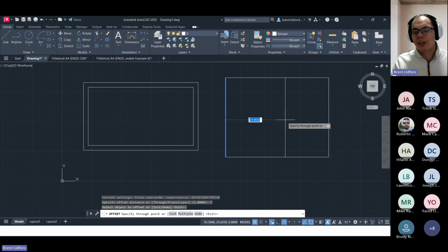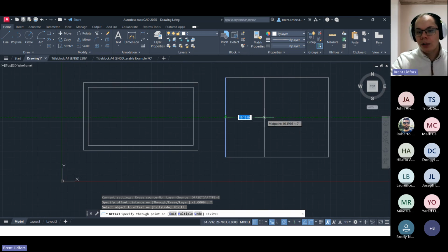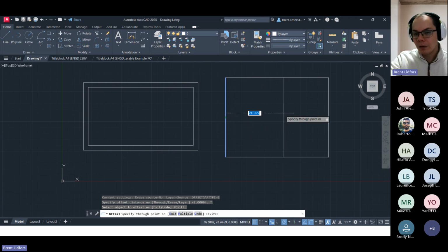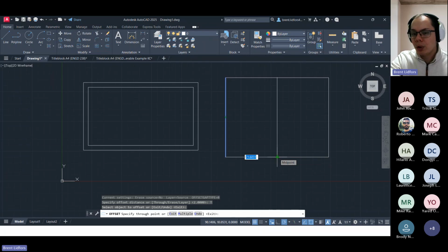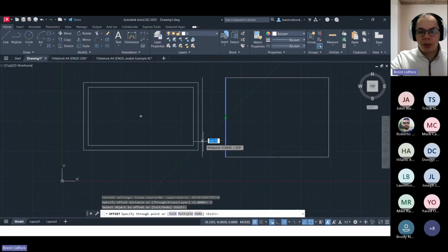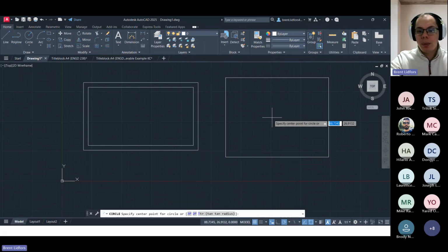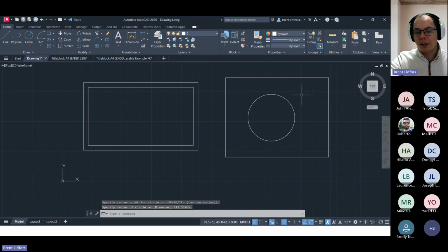the distance, or I can type in the offset distance. So it's not forced to whatever the input was. I now have a bit more free reign on how to set this offset. And this can be handy if I'm looking for something like a midpoint snap, or if it's supposed to snap to some other object. Maybe there's a circle in here and I want to offset it to kind of border this circle. I can set an offset with the through command.